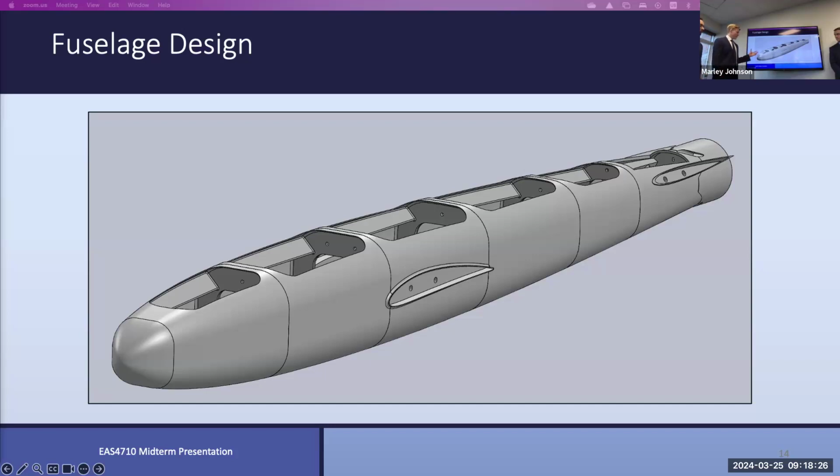The way we designed the access hatches is they're basically going to rest on top of these top two stringers, kind of like a Velcro attachment, so they should be very easy to remove and take off. They don't impose too bad of a structural load decrease. Hopefully better if you design your longerons to be your structural member, right?